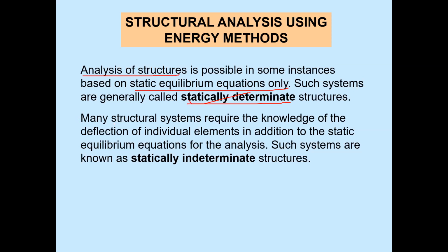Now, many structural systems require the knowledge of deflection of individual elements in addition to the static equilibrium equations for the analysis. Such structures are known as statically indeterminate. So what is the difference between statically determinate and indeterminate? We need knowledge of the deflection of individual elements as additional equations to determine all the unknowns.